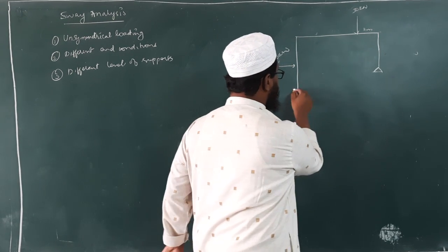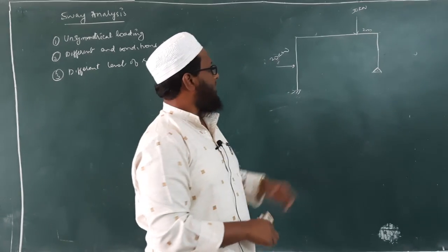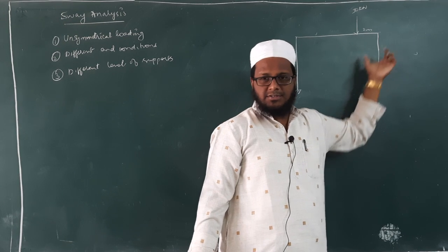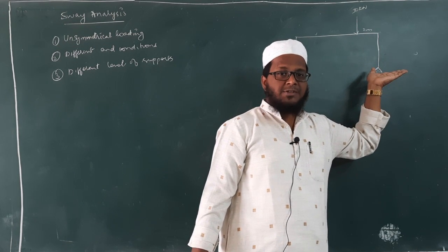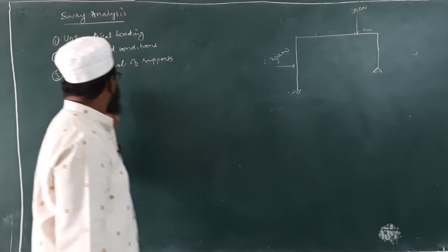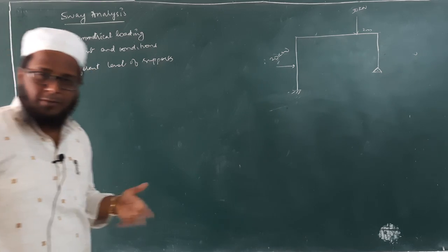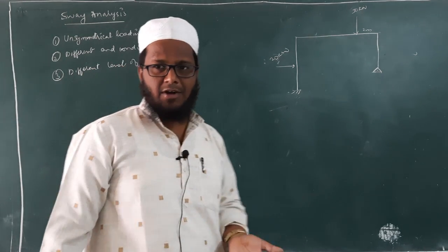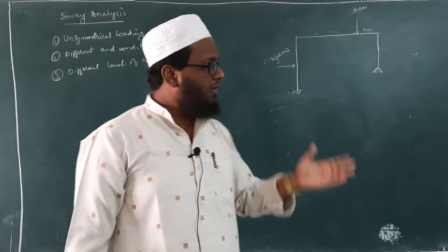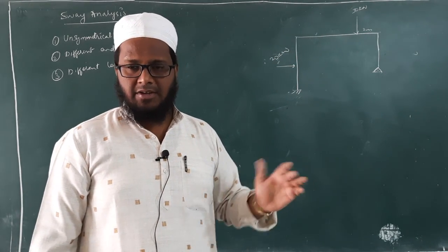Suppose this is fixed, and here we have a hinge, then this distance is different, this distance is different, isn't it? Because of that, the frame will experience sway. So these are the three conditions wherein we have to perform sway analysis. How to perform sway analysis? We'll see how to calculate extra values or deflections, because of the loading it will get deflected, isn't it? So how to calculate that, we'll see in the problems.